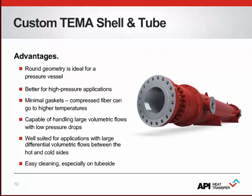So what are some of the advantages of a custom shell and tube exchanger? Well, the round shape of the shell and tube vessel makes it an ideal choice for high pressure applications. There are minimal gaskets required on most designs, and there are many varieties of gaskets available on the market that can meet the most stringent requirements where the gaskets are needed.